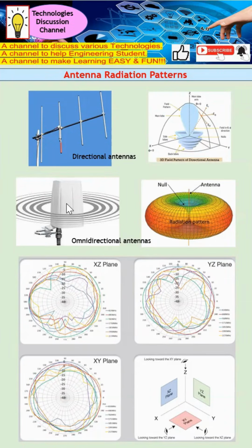Next, this can be a dipole antenna, and a dipole antenna has this omnidirectional radiation pattern. Basically, you can say that it actually radiates like a donut shape. You can see from here, right at the middle over here, is basically the null, which means that there is no radiation field that actually radiates up on top, and also no radiation field that radiates up from the bottom. As you can see from here, they basically radiate at the side of the antenna.